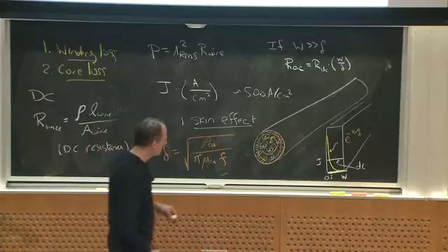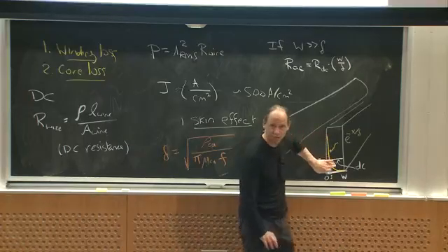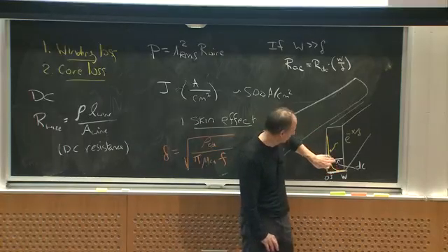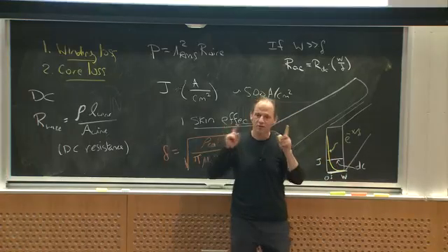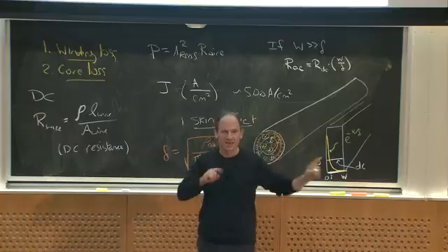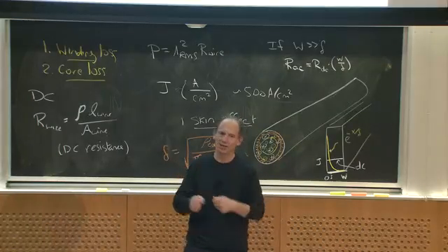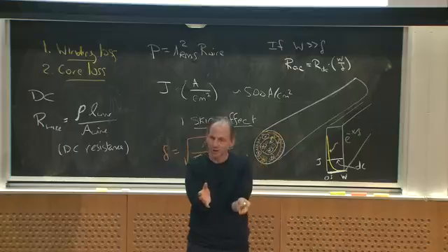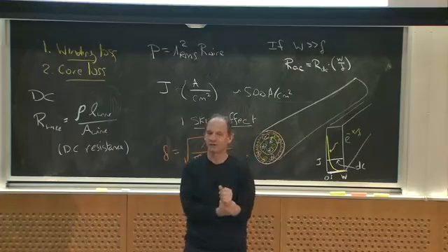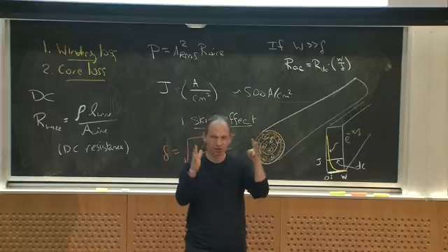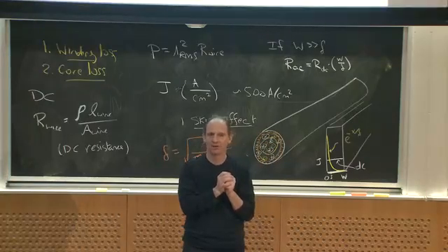Okay, so why is the current sticking to the surface of the wire, right? The question is, does it stick to this side or does it stick to this side? It sticks to whatever side of the conductor has high magnetic field imposed on it. So the way you would analyze this is you say, let me analyze where the magnetic fields are around the conductor. Where there's high magnetic fields, that's the surface of the conductor to which the current's going to get compressed. Any questions about that?